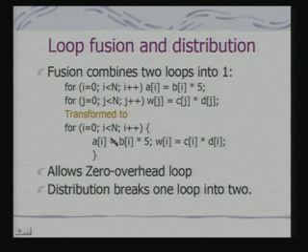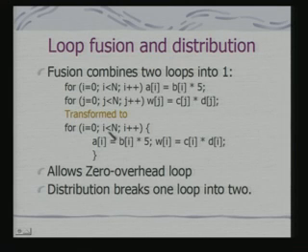In fact, once we have done this, I can reduce it to zero overhead, because if you remember, many DSP processors have support for zero overhead loops. You have to initialize the corresponding counters or registers with the number of counts, and in hardware itself the loop implementation is provided. So once I can do this combination, I can further optimize the code depending on the architecture that I am using.